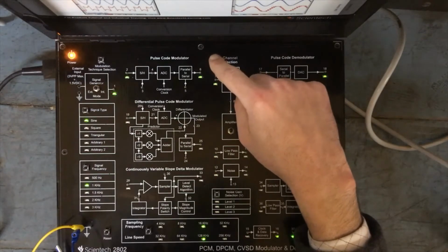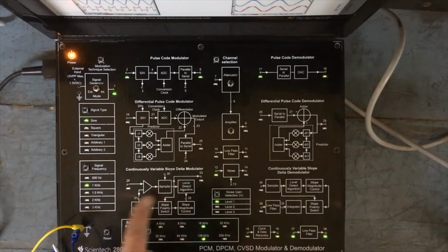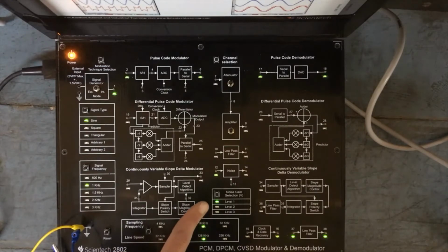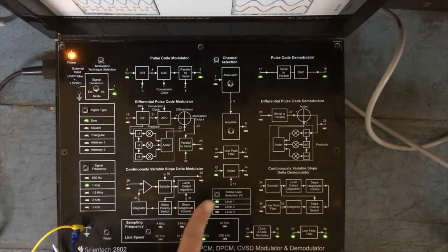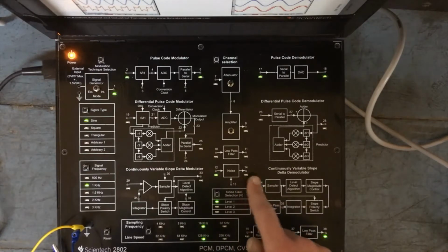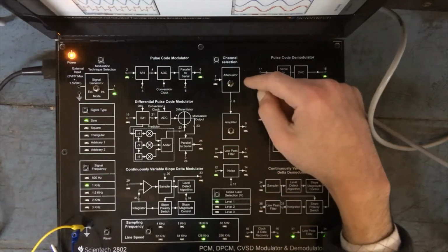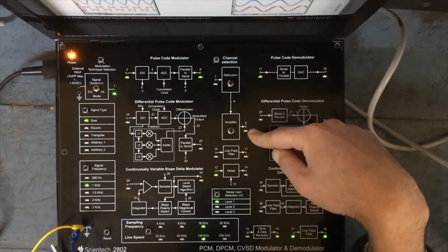Or you have the option to simply pass the transmitted signal through a noisy channel, and here you have 3 noise levels. You can select between level 1, which means the largest noise added to your signal, level 2 or level 3. Level 3 is the lowest amount of noise, which we'll see from the waveforms, and you can correspondingly give the output. If your signal is attenuated, it would be amplified through this amplifier, which is simply a gain stage.